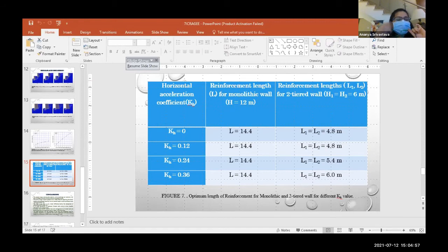I would like to tell you all that whenever we decide the offset distance, that is the distance between each tier, it is basically dependent on three factors. For my numerical modeling purposes, I have chosen 8 meters, which is very high, but it is again at my discretion that I can reduce it. So all these three walls will start to interact with each other, yet their performance wouldn't be hindered. They would still give the same kind of FOS values and the same serviceability and safety criteria. So why not construct it in a tiered fashion?